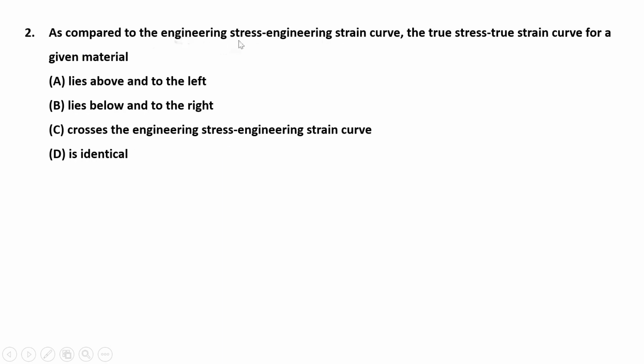As compared to the engineering stress strain curve, so this word engineering is extra, I'll remove that before submitting the PPT. As compared to the engineering stress strain curve, the true stress strain curve for a given material lies above and to the left, below and to the right, crosses the engineering stress strain curve, or is identical. So we all know about the normal stress strain curve, but normally we don't talk about the difference between the engineering stress strain curve and the true stress strain curve, but there is a difference, and we have to say which will be higher and which will be lesser, and that is this particular question.